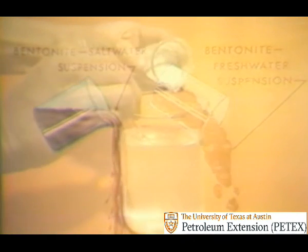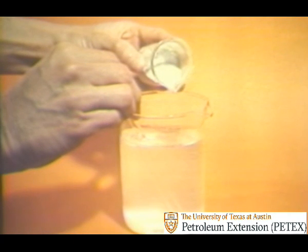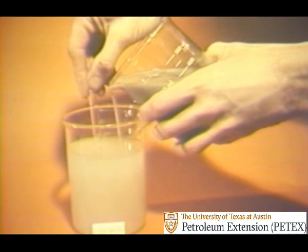However, bentonite can be used to obtain viscosity in saltwater. Here, powdered bentonite is being added to fresh water and allowed to hydrate. Then the prehydrated bentonite freshwater slurry is added to salt water and viscosity is obtained. So if necessary, viscosity can be built in salt water with freshwater clay by prehydrating the clay in fresh water.